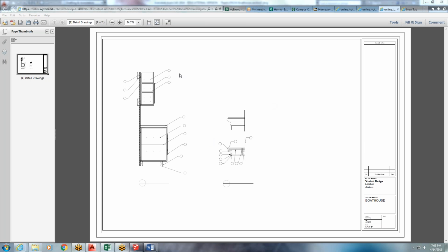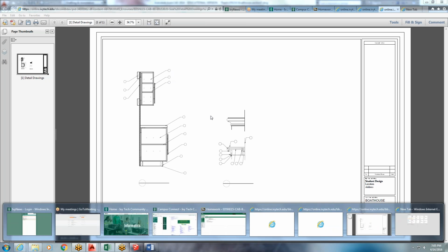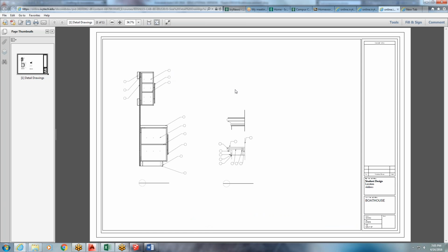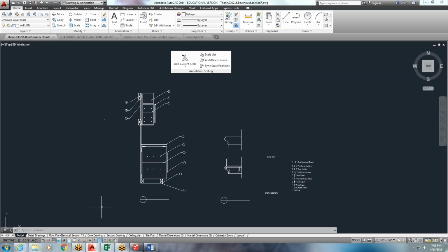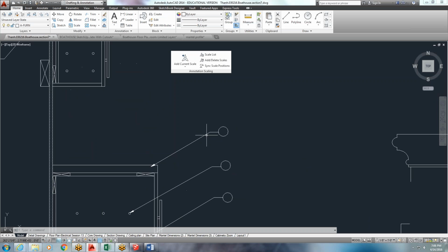So I wanted you to come in and using your leader lines, and I did it in, let's see. Oh, this is a PDF. Here I am double clicking on this like it's going to get me somewhere. I did it in the model space in the paper space, but I really don't think it makes a difference. Here, we'll give it a shot both ways. So if I was to delete this and then do leader, we'll see what the difference is. Turn my ortho off and my snap off. Okay, so there is a difference.